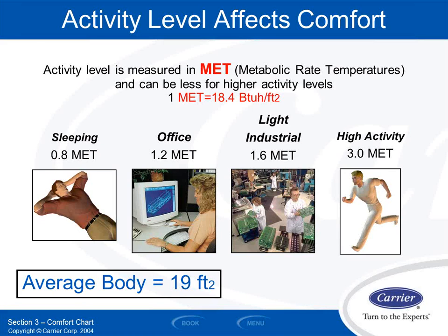So point being, if you're designing a senior home or something like that, you're going to have different targets as well. People are not going to be comfortable at 72, 73, 74 degrees. They're going to expect something in the high 70s probably for those kinds of environments. So sometimes your age does have an effect on it. The really, really young infants and the really, really elderly people are going to have different needs from the average person, being age 3 through 70, if you will.